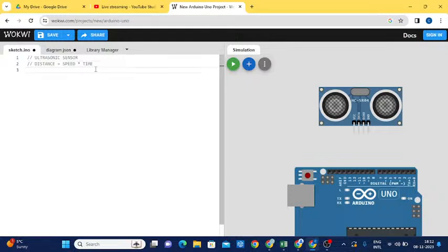Now we will move towards the coding session. In this coding session, first of all, we have to declare the pins. What are all the pins we are going to use here, and what is the working of each pin, we have to declare here. In yesterday's class, I already told you that whenever we declare any pin in the microcontroller, we have to specify the working of that particular pin. Likewise, today we are going to use the trigger and echo pins. VCC and ground are common pins.